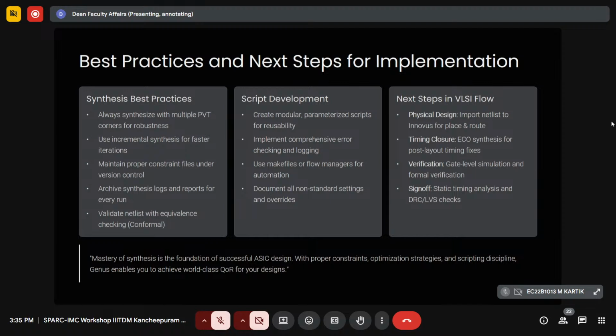It's automated now. In the industry, the run will run automatically. For example, I have 200 corners in my design. There is a flow to run the 200 corners, and you don't need to analyze each and every corner's reports yourself to make sure it is clean, as the flow will run the analysis. But if, say, 15 to 20 of the 200 corners have violations, and each corner can have thousands of violations, you need to figure out how to fix them.